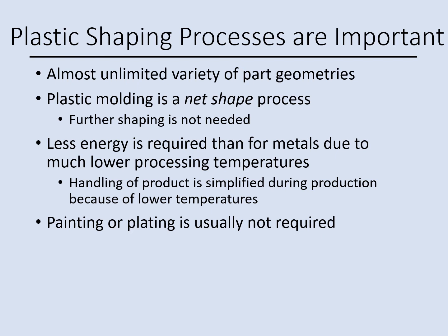The next reason is that we need heating in plastic shaping, but that heating is much less compared with metals, because metals require a lot of energy to melt. For example, if you look at aluminum, we have to heat it up to 600 degrees Celsius. But for plastic, you can use a lower temperature, maybe 100 or 150 degrees Celsius.